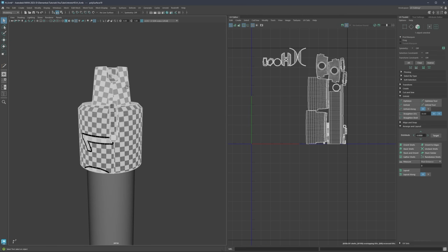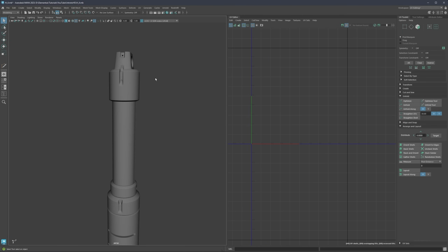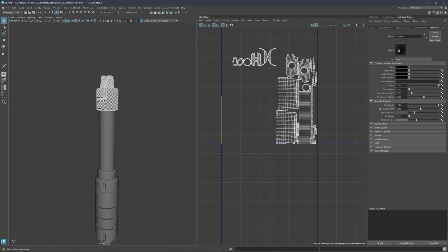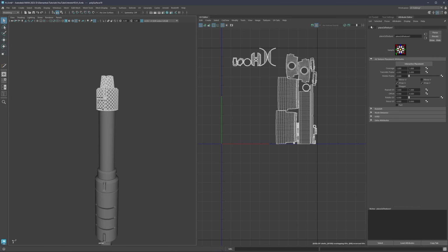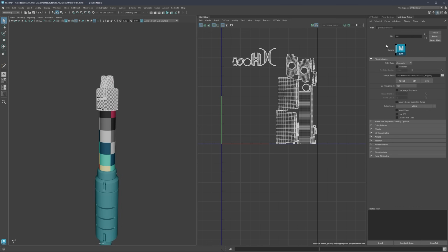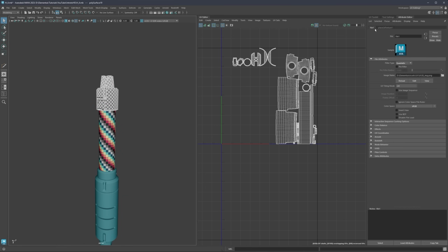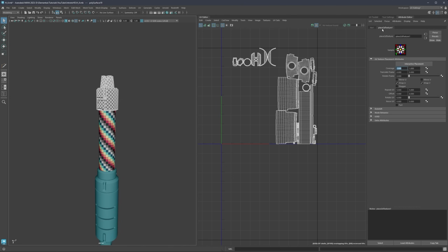Additionally, you can load in a custom texture. So for example, this is going to be our material. And let's go to assign existing materials and then this little checkbox on the side. And this will open an attributes editor. And here under color, we can simply load in a texture. And here I now loaded in a random checkerboard. We can increase the size here on the place 2D texture tab. So right next to it, you're going to have file 1. And right next to it's going to be place 2D texture. And then you can repeat UVs as much as you want to. So maybe let's double this to something like 10.